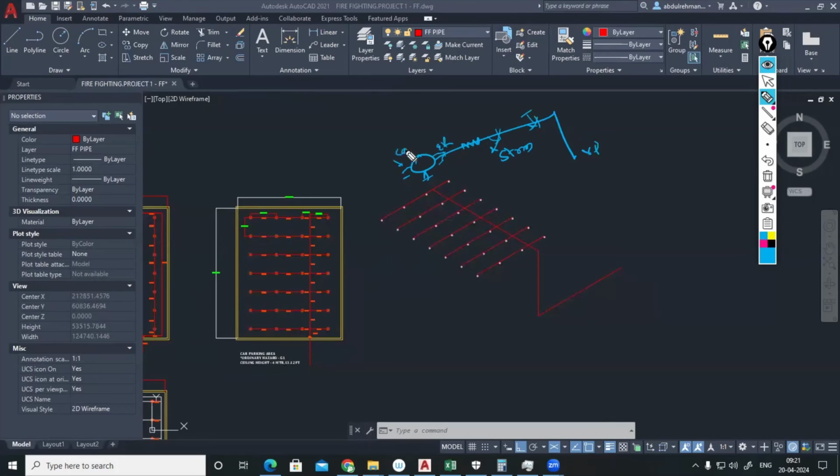Delivery, we will be having a concentric reducer, depending on the pipe size and the pump connection. Sometimes if the pipe diameter and the pump inlet and outlet are the same, you don't want any reducer piece there. Anyhow, to decrease the velocity and to prevent the vortex effect in the suction line, normally in the suction side, we will be connecting eccentric reducers only. Just for your knowledge.